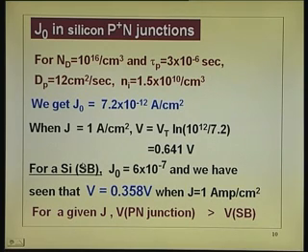So, when you say cut-in voltage, that is the meaning of that. If you actually expand the IV characteristics on the lower range, you get a small voltage. So, do not be perturbed if somebody comes and tells you the diode is conducting at 0.4 volts. It will, but at a very low current density. That is the meaning of that.